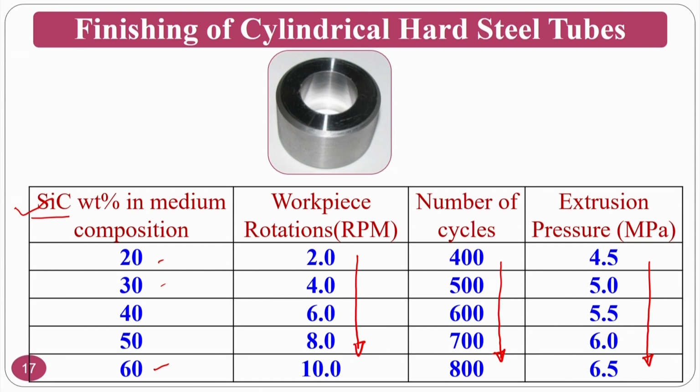If the material constraint is there, then you can go for some of the design of experimental techniques like CCRD technique, Box-Behnken technique, Taguchi, many things are there. Okay. So, those will give you the complete idea, or if you have enormous material, enormous time and other things, then you can go for full factorial complete experimentation and you can plot, that will be the best one.